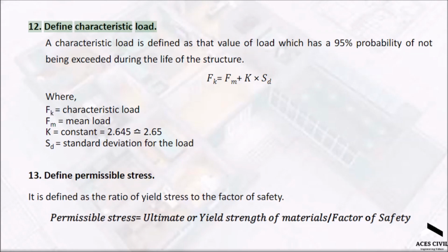Define characteristic load. A characteristic load is defined as that value of load which has a 95% probability of not being exceeded during the life of the structure.